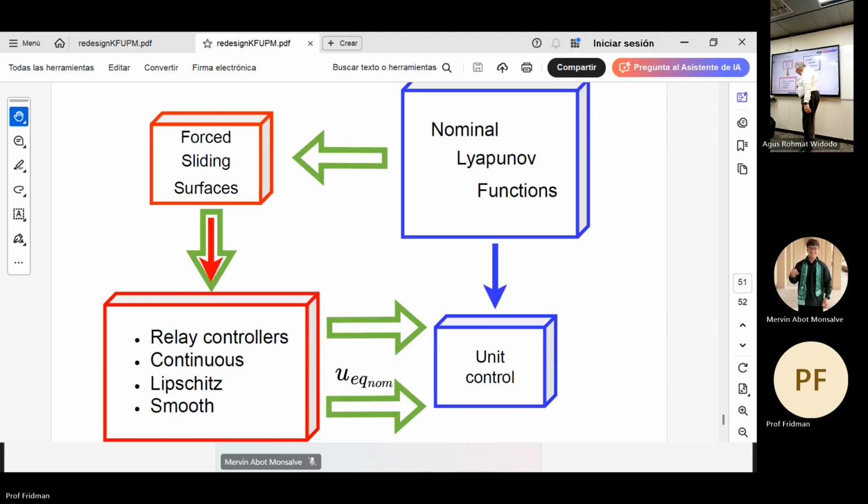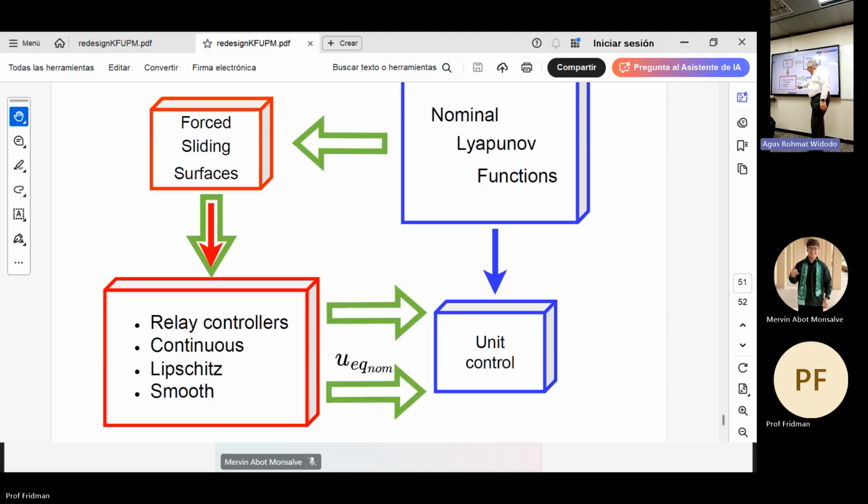And then there is one other story: all of the things which you are able to compensate, you will not compensate through policy. You just need to correct the control law, and that's all, without any change. Okay? Because chattering, if you would like to compensate uncertainty, if you would like to compensate perturbations, you cannot avoid. But at least we need to make the chattering a little bit less.